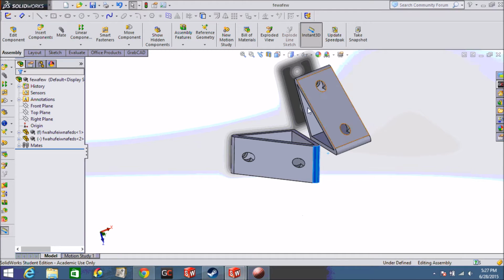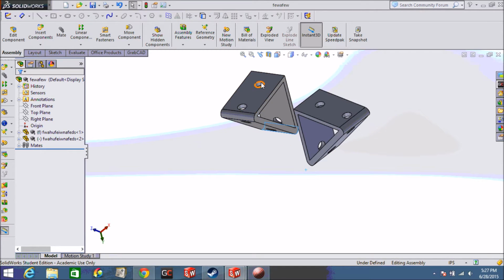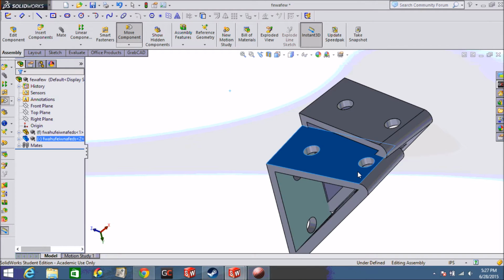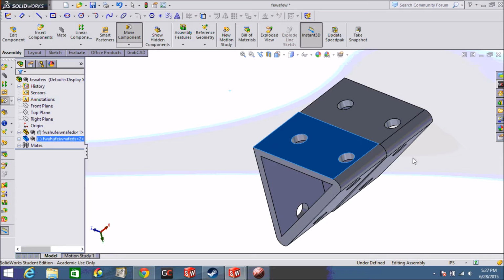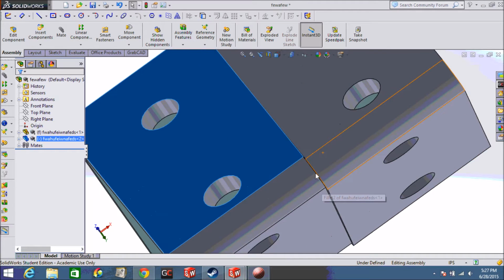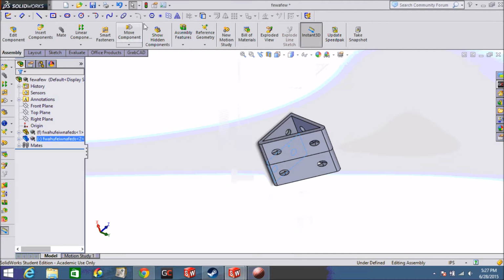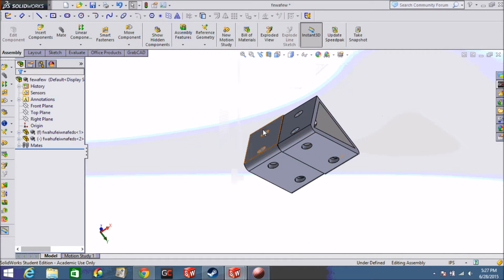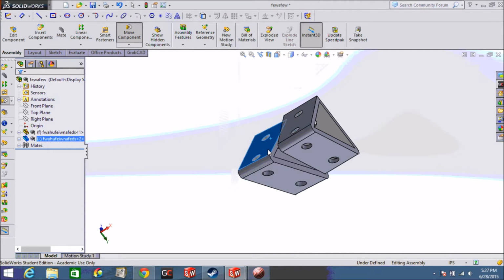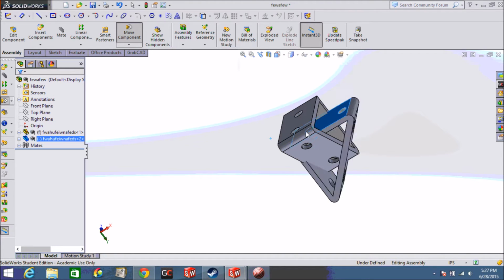Rebuilding is basically re-rendering your assembly. So Solidworks has some optimization that allows it to not take a million years every time you change a little small thing to re-render all of what you've done. However, sometimes this will create small issues where objects that you've already deleted still appear, etc. So it's a good idea before you save to just rebuild your document.